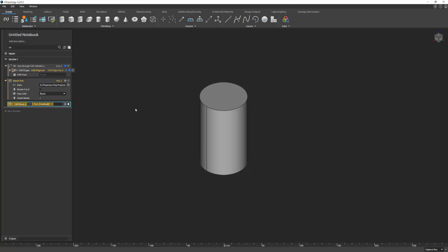The reason being is I like to often reference CAD entities during my design process to make the workflow as parametric as possible. So for instance, if I want to capture this CAD edge and this CAD face, I drag them into this CB, and I'll get an axis created through here. Now if I go back to my CAD data, update a fillet or add a hole, then this CB and this axis that I'm referencing for, let's say, a downstream operation may get updated.